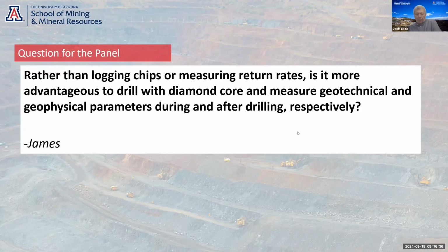And the thing with injection tests is you just have to think about the unsaturated zone above the water table, whether you're going to lose fluid into that unsaturated zone. But as I say in the course, you can normally tell if that's happening. So injection tests is something we're doing more and more of. They're easy to do because you can just lower in a transducer and pump in water, and so they're a great way to provide hydraulic testing of the formations when you don't have the ability to airlift.